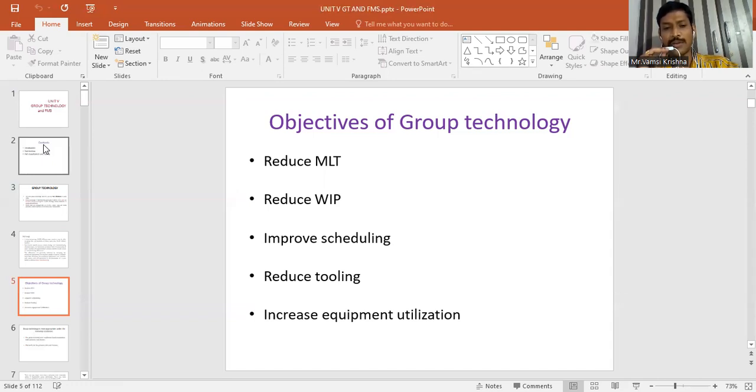The fourth objective is to reduce the tooling. Instead of having redundancy, that means repetitive usage of the tool, if the layout is assigned properly, with minimum requirement of tools, we can produce higher production. One of the important methods in optimizing productivity is considering the respective tool wear rate for a material removal rate. Material removal rate is relevant to the workpiece.